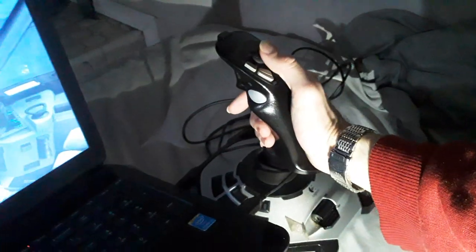Also we have the alpha protection system, the alpha floor for 1 G stall when we reach the airspeed and the angle of stall. So we will set the takeoff go-around thrust automatically locked, and it will limit the angle of attack of the aircraft until we exit the stall. Also maximum speed, minimum speed protections. So this is a fly-by-wire system. The fly-by-wire for the Airbus is similar to the Boeing.